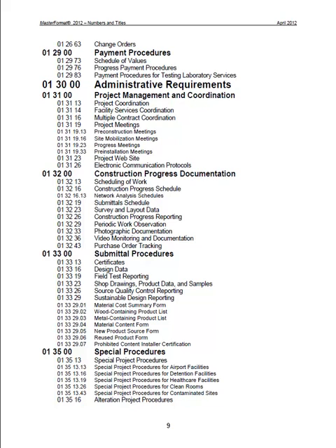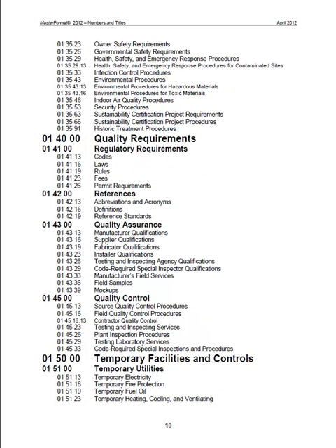The worst thing that can happen is to get something on the job site installed behind walls that you suddenly determine does not meet specification and it has to be taken out. So it's very important that these things be looked at prior to installation, and it's a protection for the contractor to supply things with submittals from a manufacturer so that they are assured that what they're putting in has been approved by the engineering firm, the design construction firm.